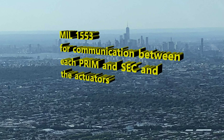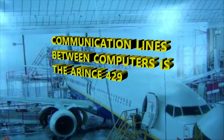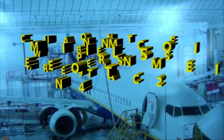Okay, so between the computers and the actuators, you have to have a network, and that network is the MIL 1553, along with couplers. And when we talk about communication between computers, we're talking about the ARINC 429. Otherwise, it's the MIL 1553.